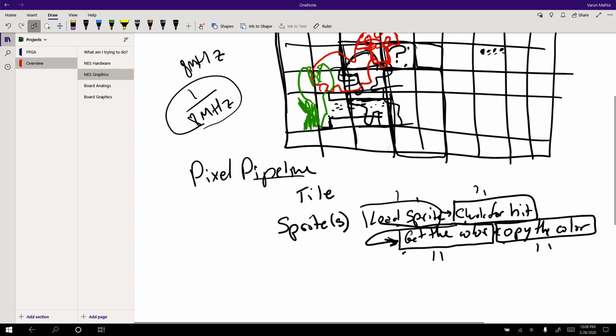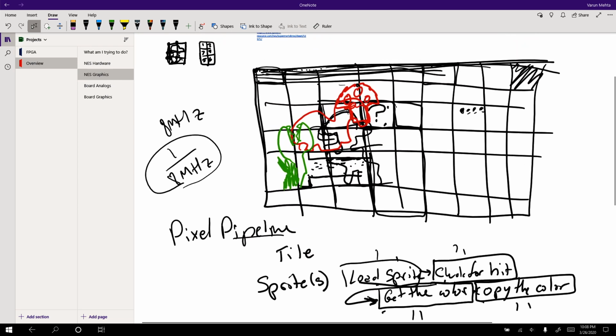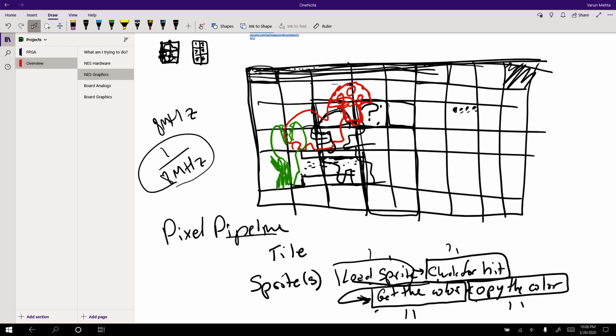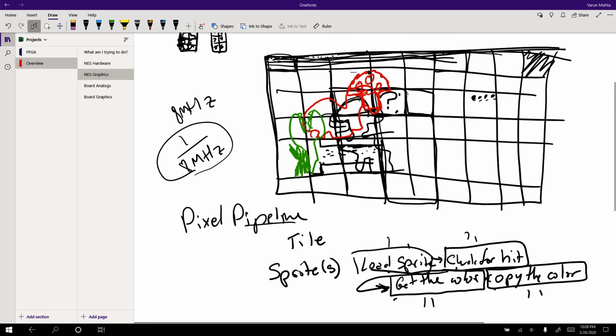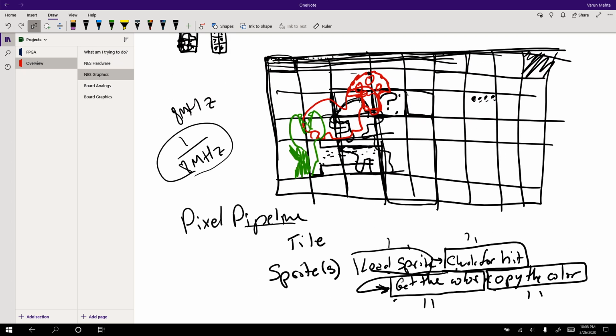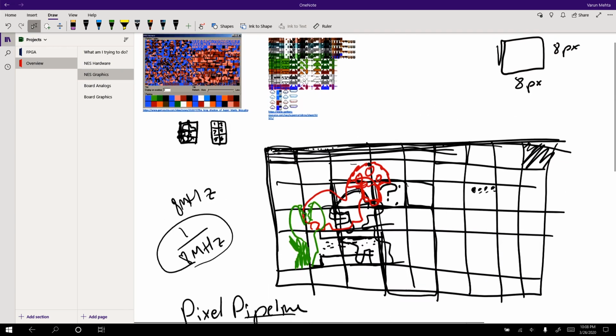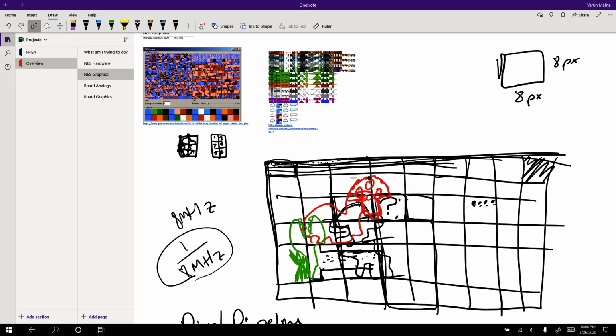And the truth is that even in modern hardware design, as much as possible, you'll find that this pipeline concept applies. Even CPUs today will have a pipeline, because think about it, a CPU runs code, but in order to run the code, you still need to fetch the code from memory and then decode what that code is telling you to do, and then perform the operation.